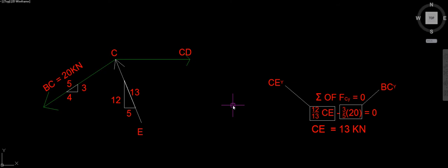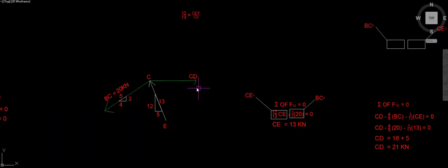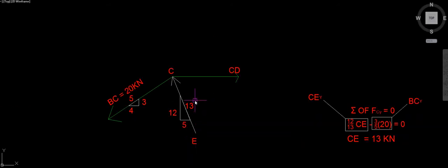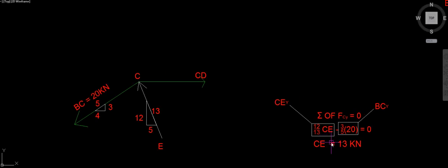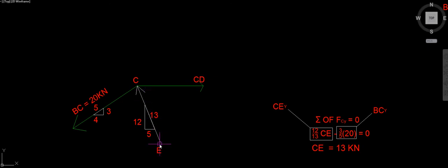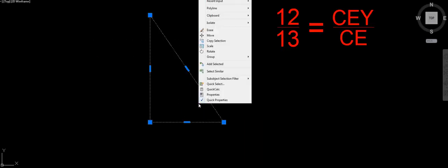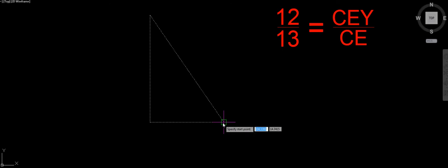I just paused the video and I thought to myself, maybe I should do a small equation that shows you guys exactly how I got this 12 divided by 13 times CE equals the y component of the force inside member CE. And this is actually where it's coming from. If I've got a triangle, and I've got another triangle.